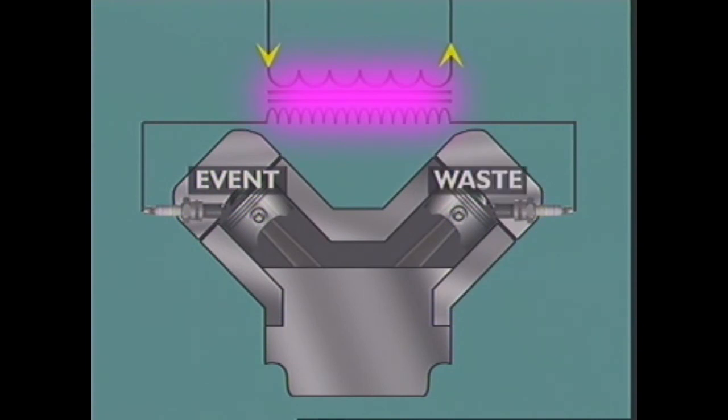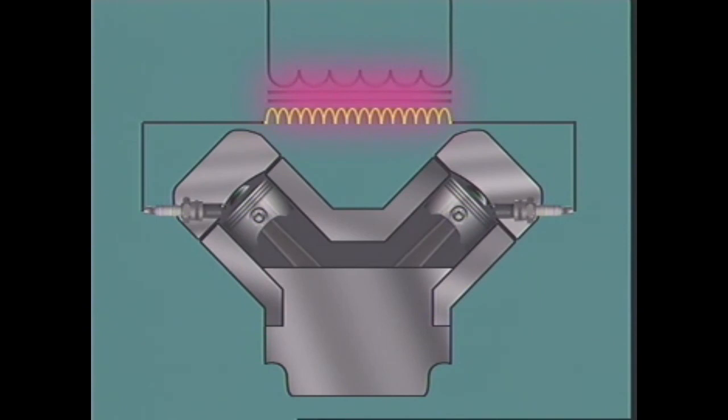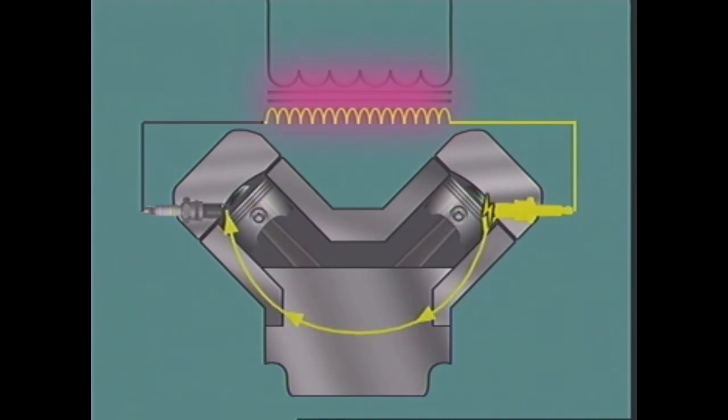is the waste cylinder. When the high-tension voltage is induced in the secondary winding, the secondary circuit is completed by current flowing through the high-tension lead to the center electrode on one spark plug, bridging the gap and creating a spark in that cylinder, traveling through the cylinder block, bridging the spark plug gap in the companion cylinder, and flowing back through that high-tension lead to its starting point.